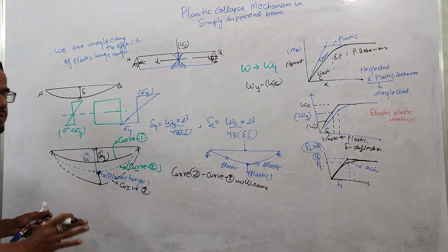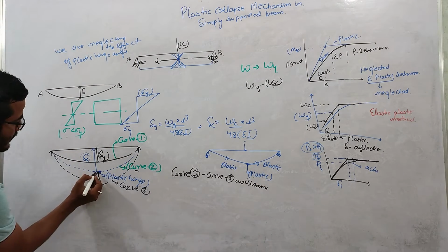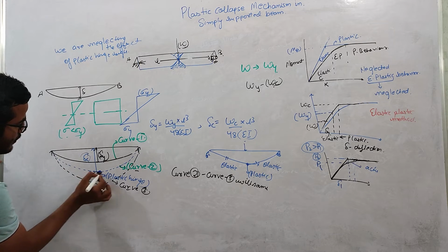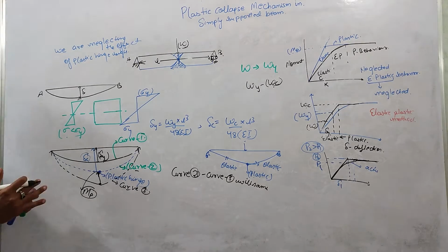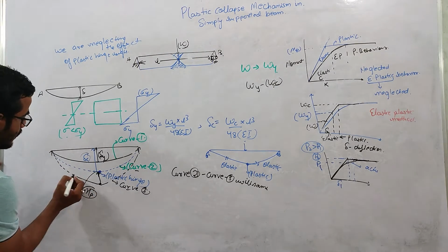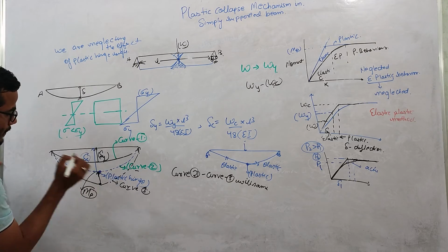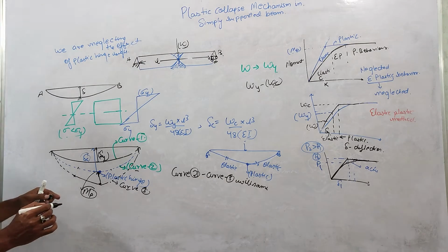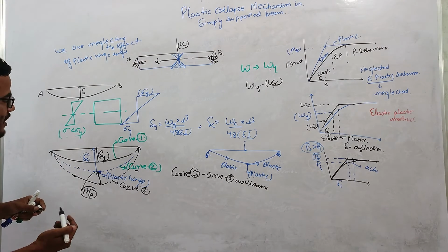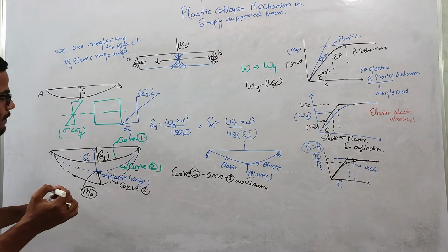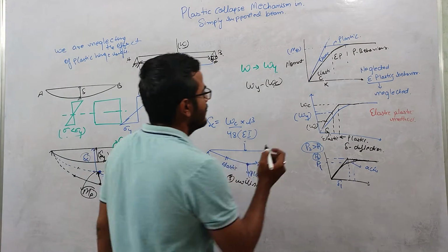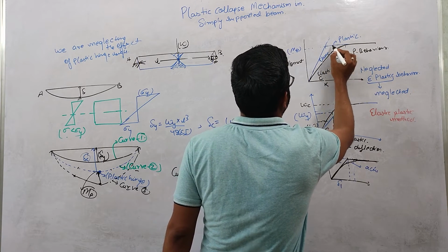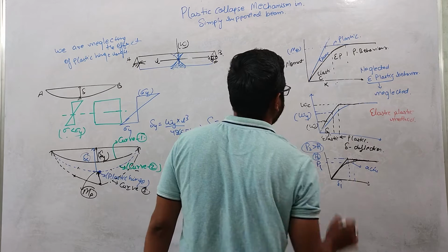Okay. Because the moment capacity is not increasing. This section has already reached the MP state. Okay. So it has some deflection curve. These are basically bending deformations. Beyond that, it cannot provide any resistance to bending. Okay. So these two curves will be the same, right? But after the formation of the plastic hinge, it will deflect with constant load. Okay, that you can see here. When it reaches the MP, there is an increase in curvature at constant MP, right?